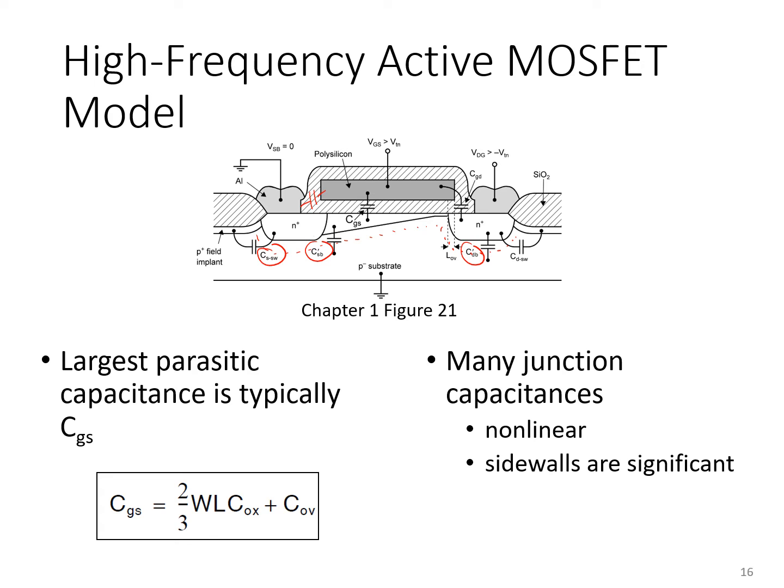Another important point to note is that in some technologies, the way transistors are isolated from other neighboring transistors involves introducing a relatively heavily doped region in the body terminal area here to ensure that no parasitic channel is formed between, let's say, this NMOS transistor and its neighbor here.